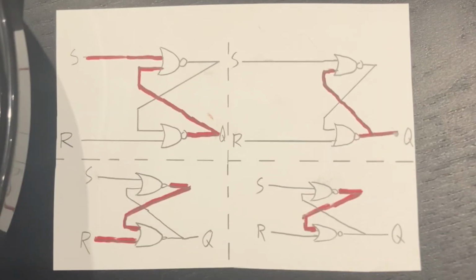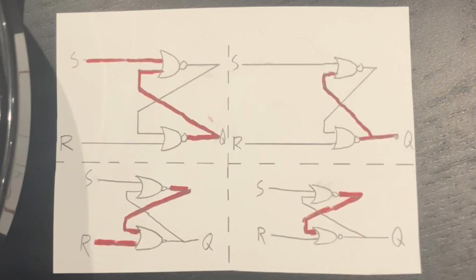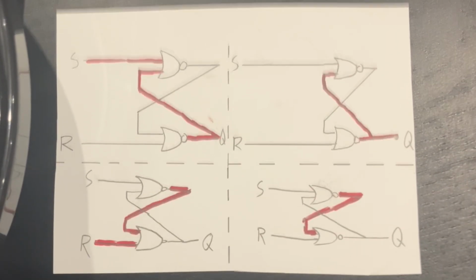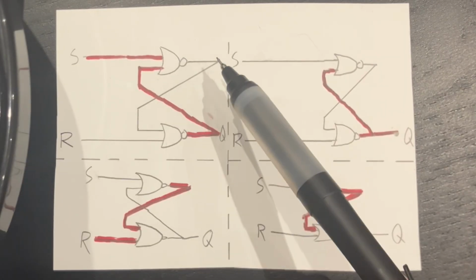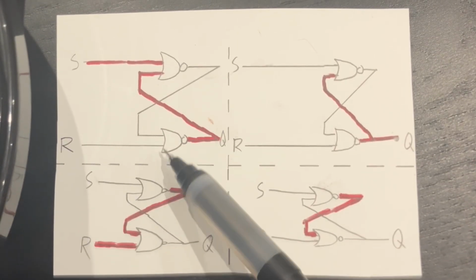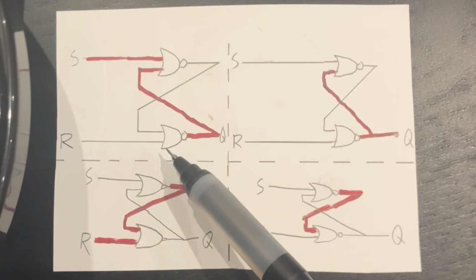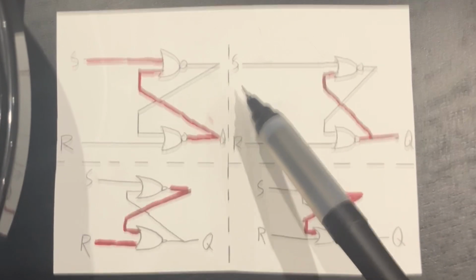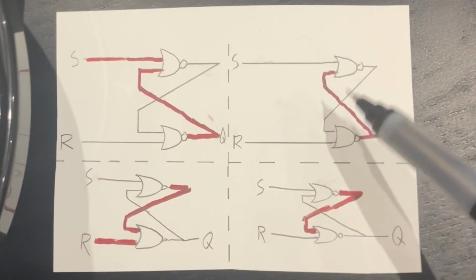For the bistable 555 memory latch, when the left PBNO is pressed, it essentially drives the lower comparator, the set comparator, high. First NOR gate outputs a low, which means that there's two low inputs on the bottom NOR gate, which outputs a high. So then even after the PBNO is released and set goes low, it holds this value.